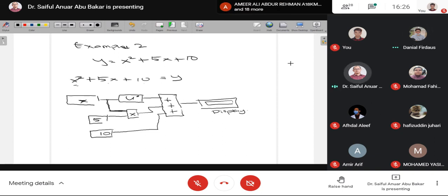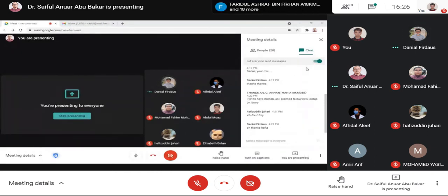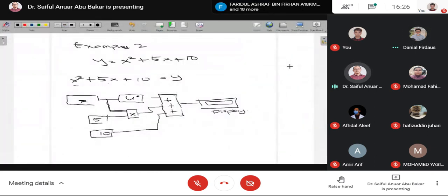Doktor, for the X block, what is the name of the block? Constant. Constant. Oh, okay. Constant, then you double click, then you change it. But you have to enter the value in the main MATLAB interface. Just to declare the value for the constant, right? Yes, just type X equals any value you want to use. Alright, thank you.